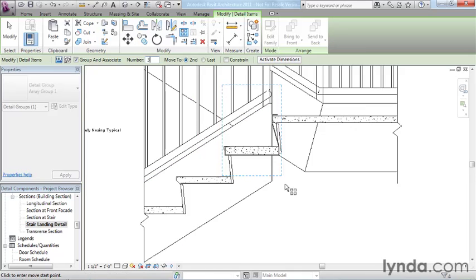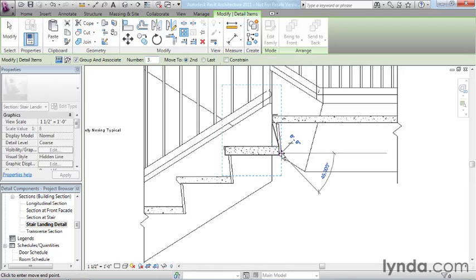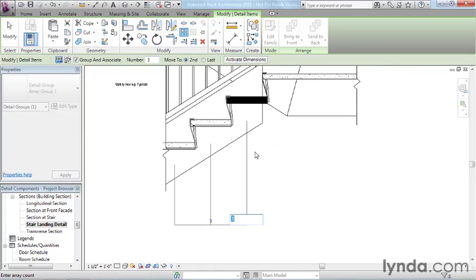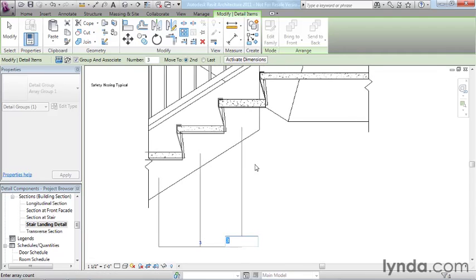And then my job is to indicate to Revit somehow that spacing that I want to use. And the easiest way to do that in this case is going to be to object snap right here, and then object snap the corresponding point on the next tread. So right there. And what you'll see is, if I zoom out just a touch, the 3 items array in a stair-step fashion, and then this temporary dimension appears down at the bottom.